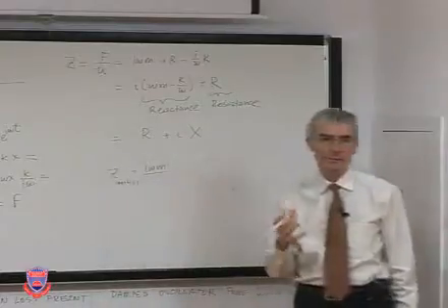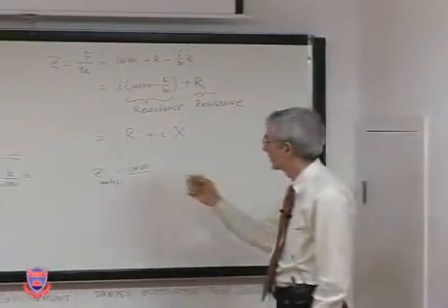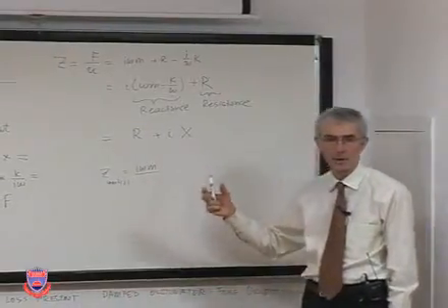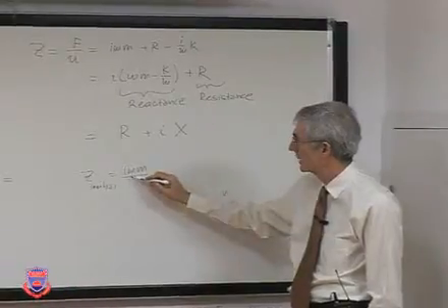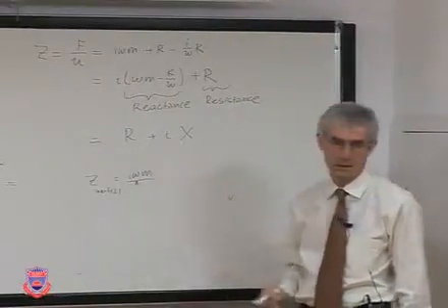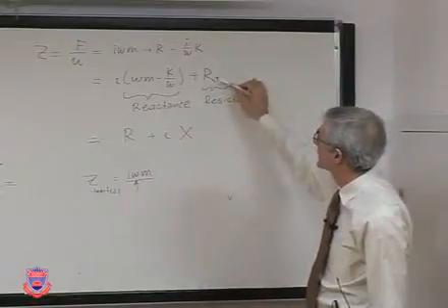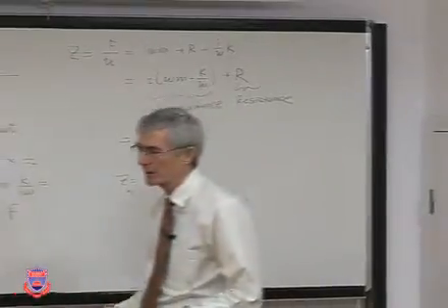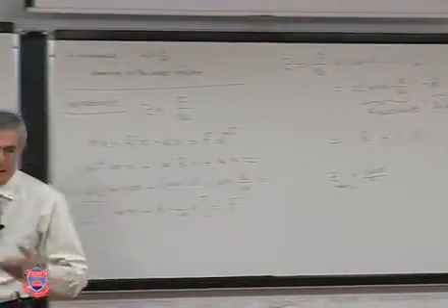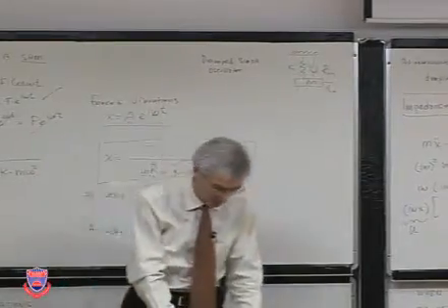So when you have just a mass that you're pushing through, or you're oscillating somehow without any springs or losses, this would be the impedance of just a mass. It's called the inertial impedance. And so you can see each one of these are the impedance effects. And in electrical engineering, there are similar types of impedance expressions for electrical systems.